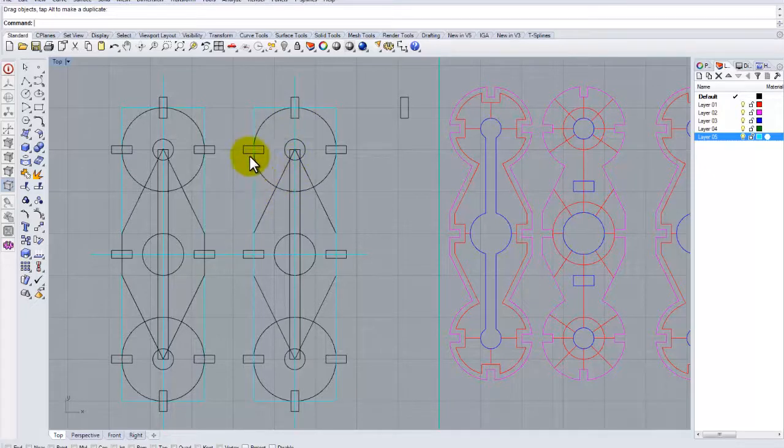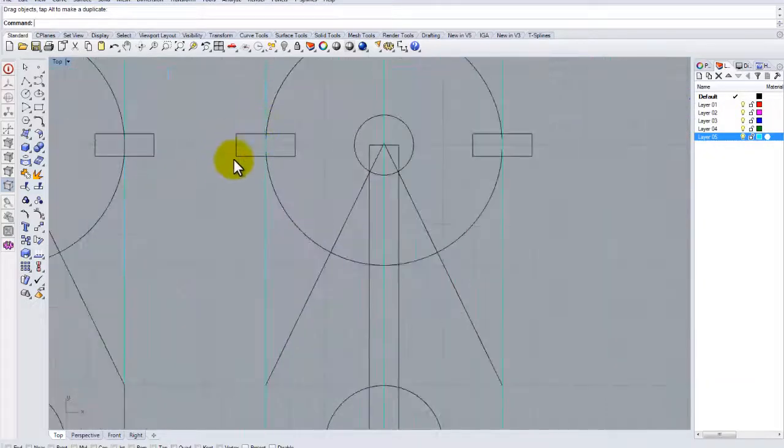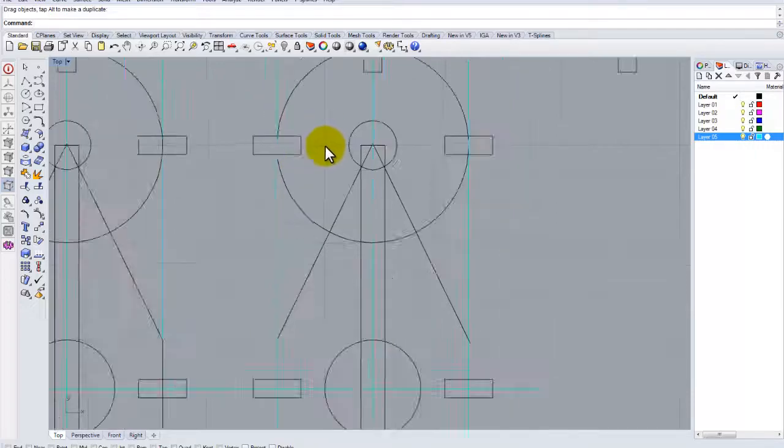The other thing that you should note is that it's a half lap intersection. So half of the piece is going to come out this way, and the other piece will come to this point here. So whatever your notch thickness is, when you're doing your design, you should note that it really doubles in width, and that's where the other piece will interlock with this.